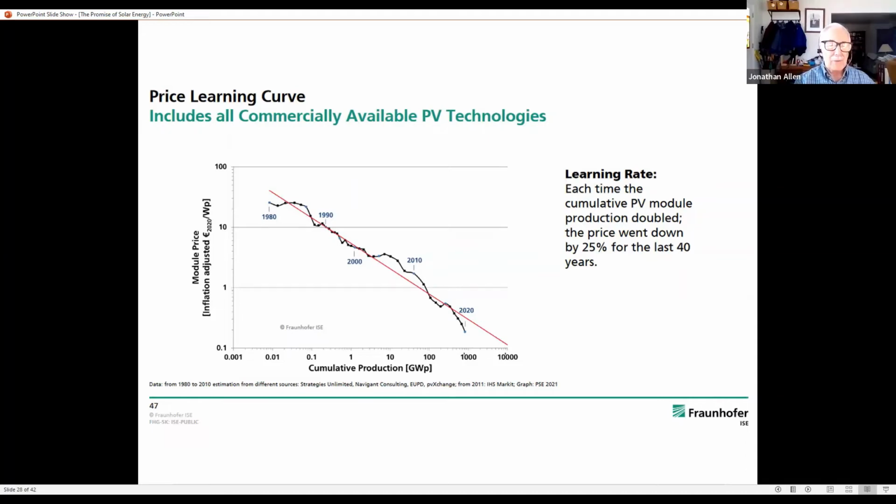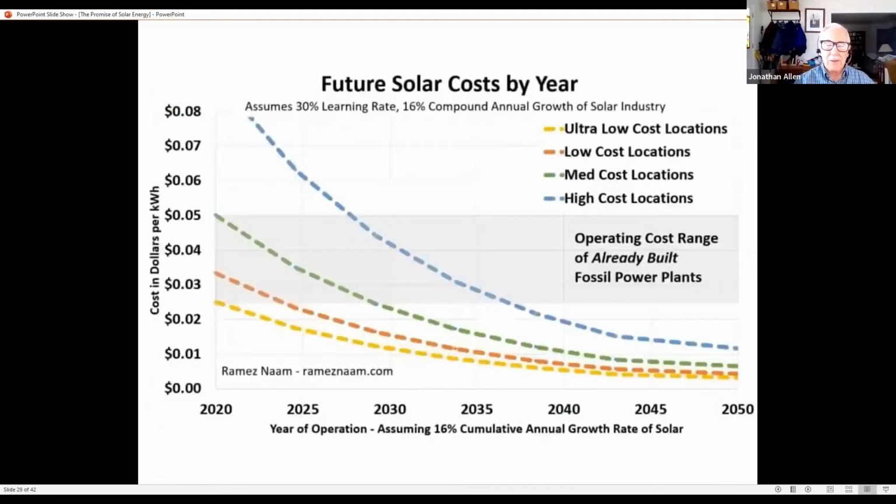And the same guys who drew this curve have dared to project the future. And you can see that depending on the application and such, we're talking about dropping from about 8 cents for the most costly, to about 2 or 3 cents for the best, down to perhaps a penny or so a watt. There are two common indices for cost-benefit analysis: energy payback time and economic or money payback time. The first asks, how long does it take to generate as much energy as it took to produce the panel? Obviously, it takes energy to manufacture it.